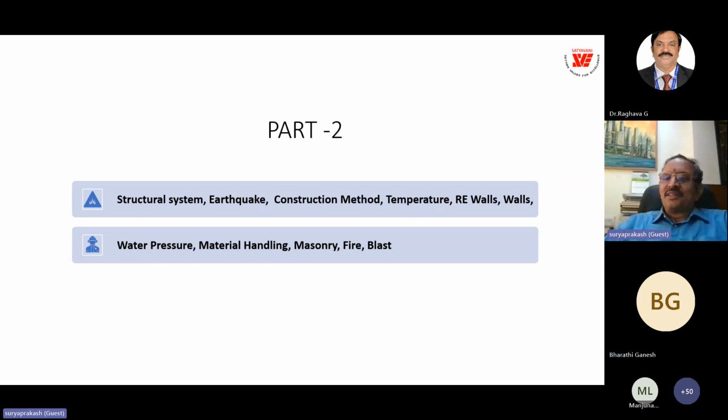Yeah, this is a very big problem that entire humanity will be facing with urbanization, actually. We have runoff coefficients for rural areas, agricultural land, and urban areas. In urban areas, your runoff will be much higher because the absorption coefficient is very low. We are covering the entire area with concrete, pavements, buildings and all that due to human occupancy.